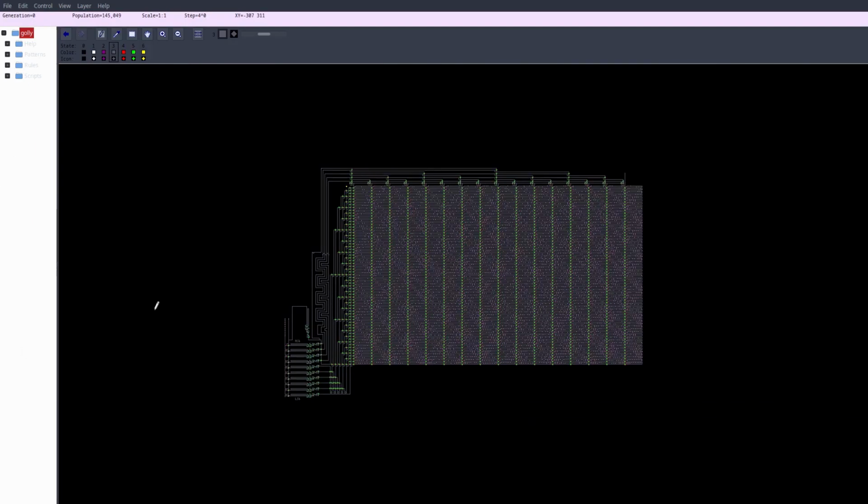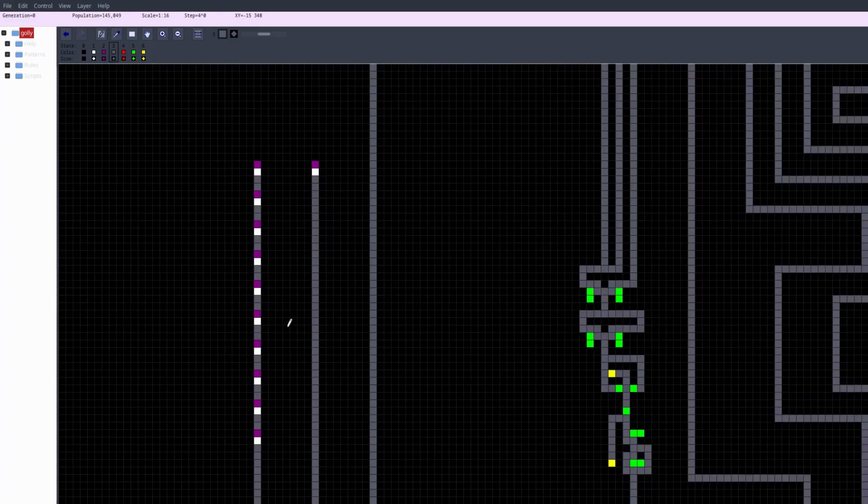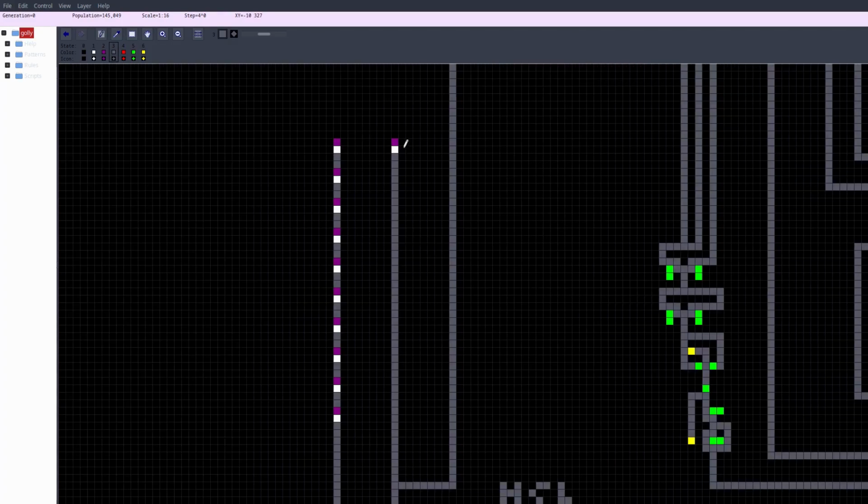This is the ROM used in the final design. If you're watching this full screen on a 1080p display, each pixel is 1 cell. The ROM can hold up to 1024 instructions, each of which is 18 bits long. At the bottom left is the input. On the right is the clock input. On the left is the address, which is 10 bits long.